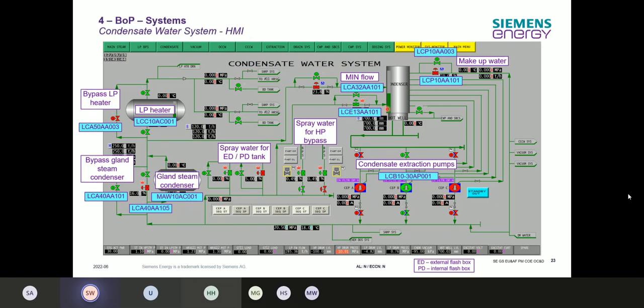When you would increase the flow to the boiler, so you're increasing your load, so you can produce more steam in the boiler, more steam will get through the steam turbine. So in the condenser, the level will go down. So you need to refill it.